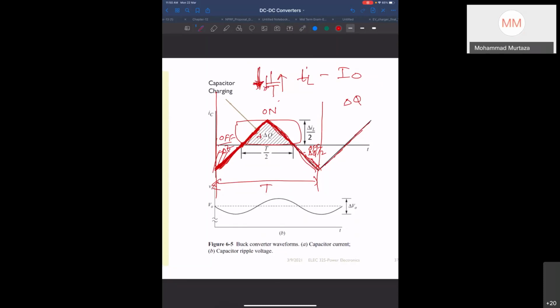Yes, perfect. So what is happening here? We have to find out how much charge it gets when the current input to the capacitor is positive. Current is rising and falling, but it is positive all the time from here to here. So how much charge does it get? To get the charge, we just have to find the area under this curve. And you see, this is how the output voltage variation will look.